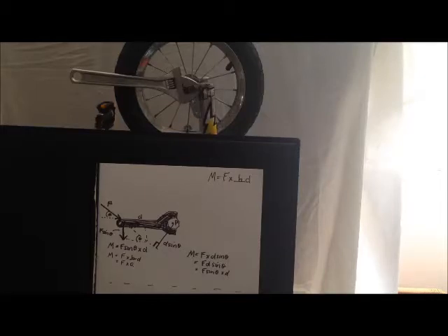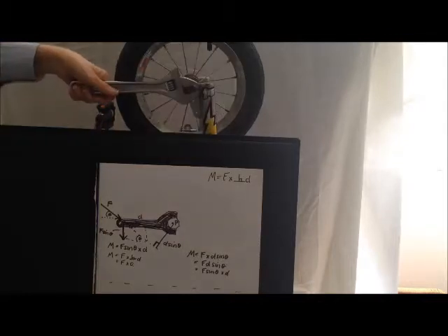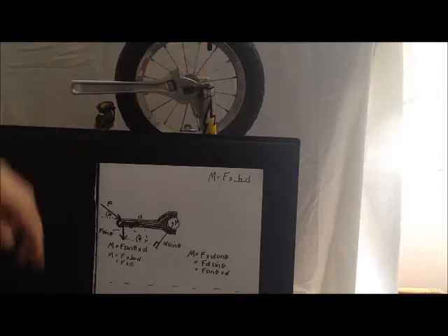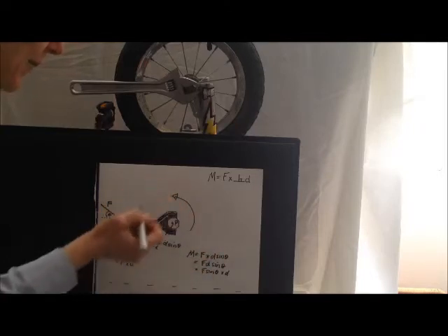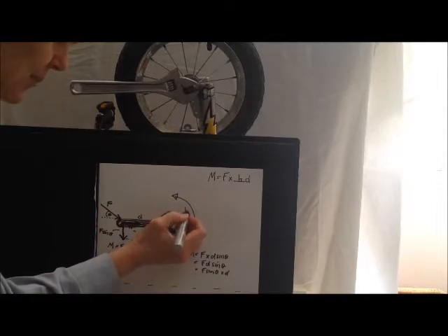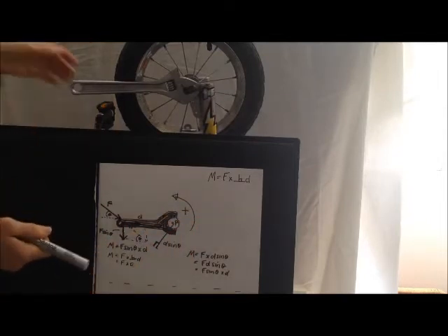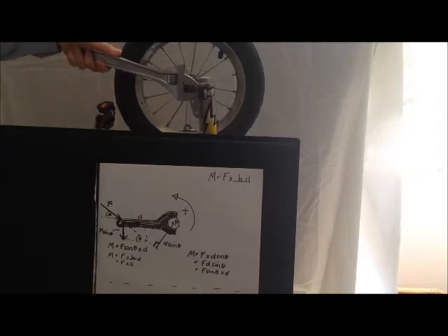Now, remember that moments also have a sign. Here, when we're pushing down the spanner this way in the nut, we're pressing counterclockwise. And we know that when we're pressing counterclockwise, in order to achieve the goal of loosening something, which is where the effort is required, that's the positive direction. That counterclockwise twisting is positive. The spanner will twist around that way, the bolt will twist around that way, and that's positive. If we were tightening the bolt, then we're creating a moment in the negative direction. Positive when we're loosening.